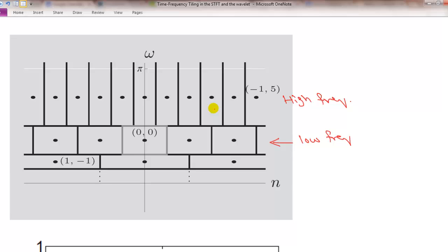Just like the discrete Fourier transform, if you have a length-n signal, you don't really have to explicitly compute it. You can use algorithms like the fast Fourier transform to compute it in order n log n computation time. Discrete wavelet transform can also be computed in a very fast fashion. Discrete wavelet transforms can be used for spectral analysis if you are interested.